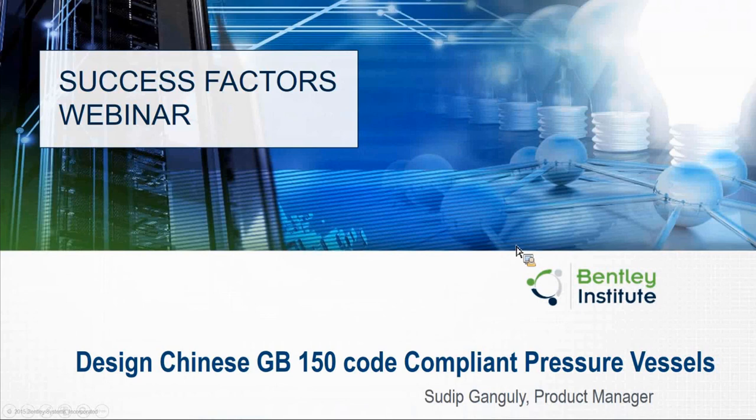I have a question here. What all codes are covered other than GB150? So like I mentioned, AutoPIPE Vessel offers a total of 7 codes: American ASME, British PD5500, EN, German AD Markblätter, GOST, Russian, CODAP, which is the French code, and GB150.